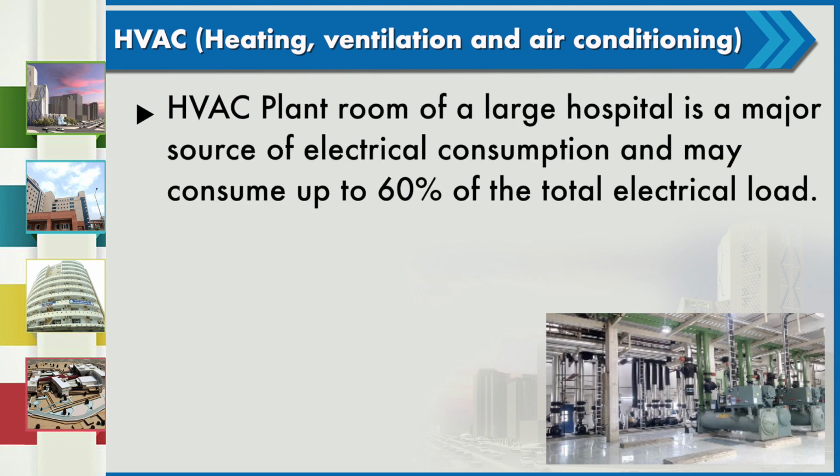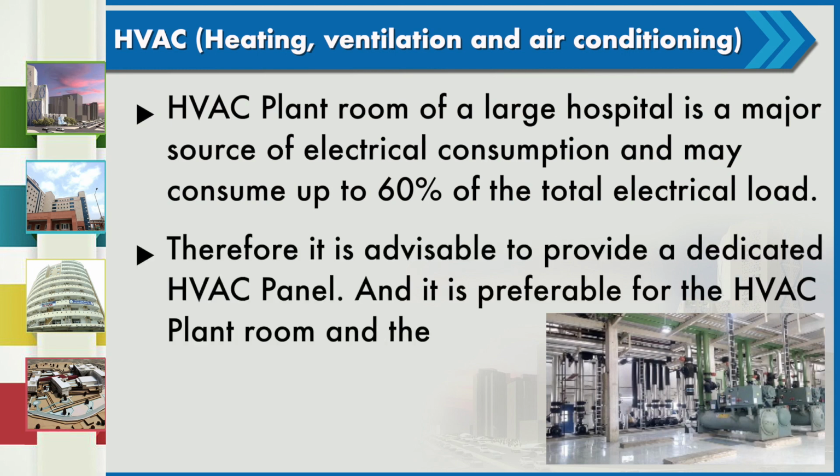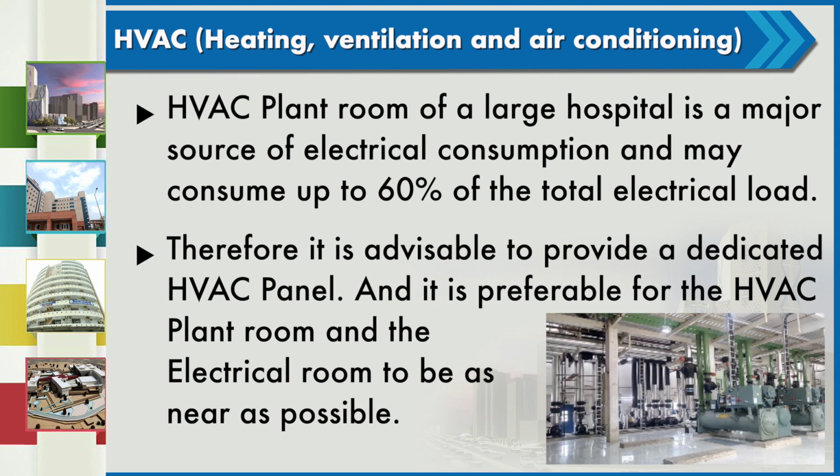The HVAC plant room of a large hospital is a major source of electrical consumption and it may even consume up to 60% of the total electrical load. Therefore, it is advisable to provide a dedicated HVAC electrical panel and it is preferable for the HVAC plant room and the electrical rooms to be as near as possible.